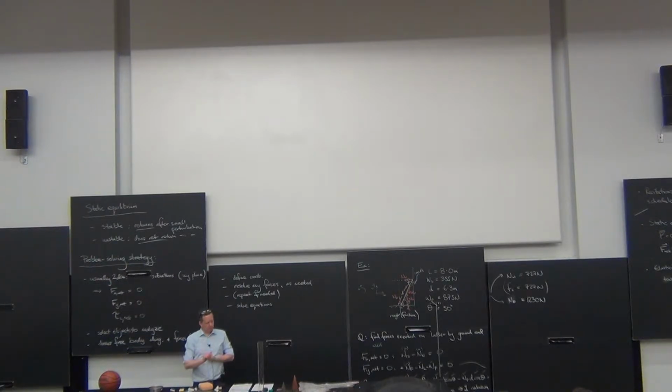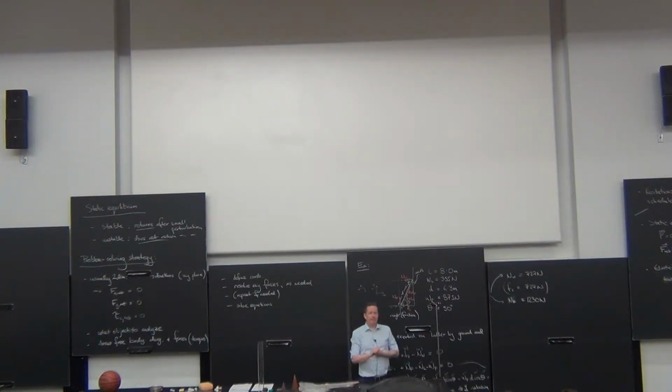In the previous questions we had with the ladder, the force from the wall always has two components. Why is it in this one it just has one? Simply because this is a smooth wall, right? If there was some friction at the wall, I'm going to add a friction component, which is going to be parallel to the wall surface. But in this case, I've defined it to be smooth.